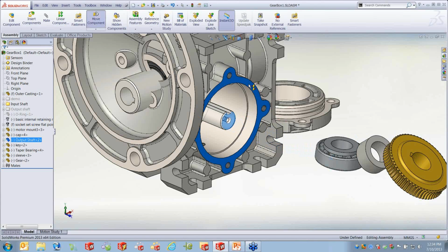Okay, so if I wanted it tangent or parallel or any of that stuff, well, if I want this shaft coincident with the end, I can drag the two faces to each other, holding down the Alt key. Once I let go, it brings up the mate dialog. Well, maybe I wanted this to be a distance. Well, this is going to be 2 millimeters. I can even do my flipping. So even though it says for common mates, you can still get to the other mate types using smart mates.